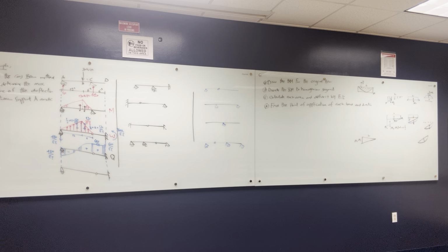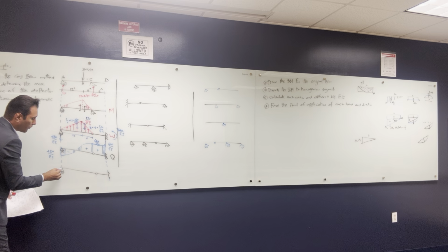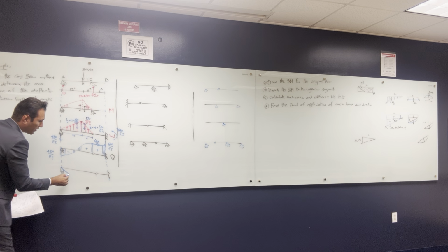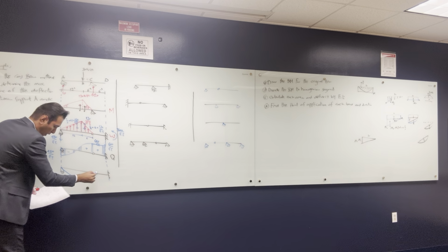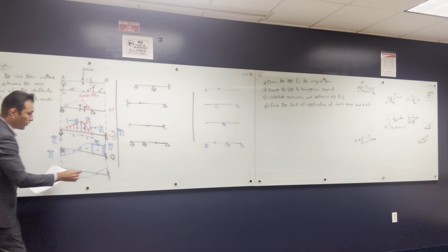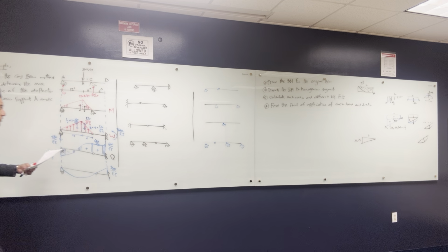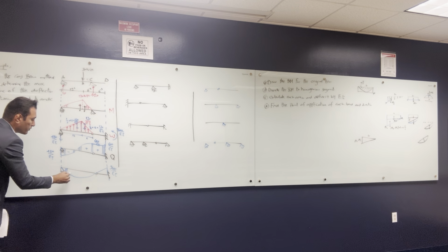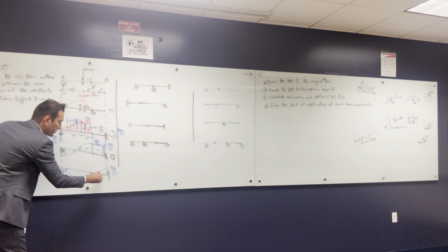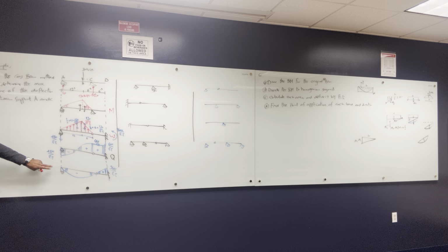The bending moment diagram, if you draw it for this one, the moment here is 0, and the moment here is 0. So you will find out that the moment shape is something like this. And then it goes up something like this. And the value here, you'll find it as 3600 over EI. Okay, that's the bending moment diagram. Right now, this is negative, and this is positive.